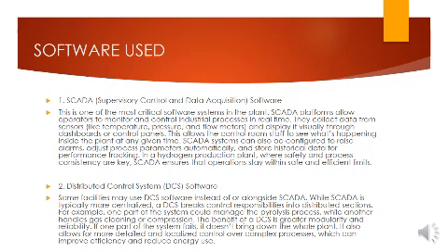This helps maintain safety and process consistency within the plant and ensures that operations stay within safe and efficient limits. Then we have DCS, which is distributed control system, because it allows for more detailed and localized control over complex processes, which can improve efficiency and reduce energy use. It is sometimes used in connection with the SCADA.